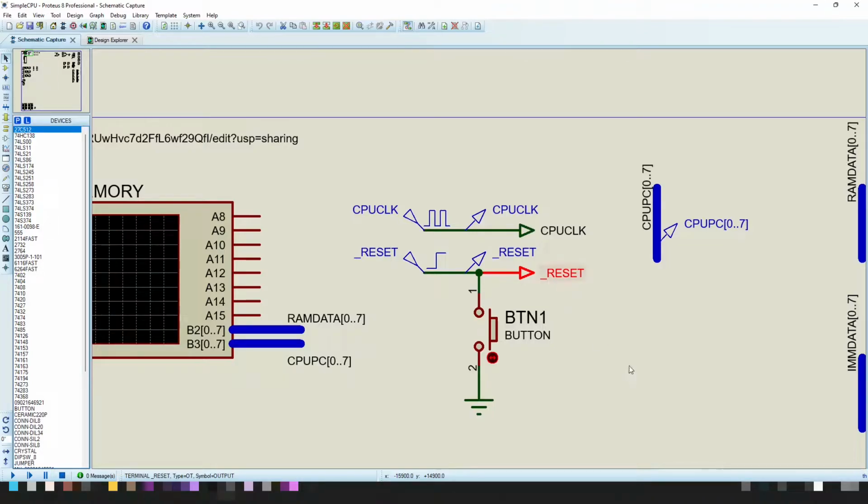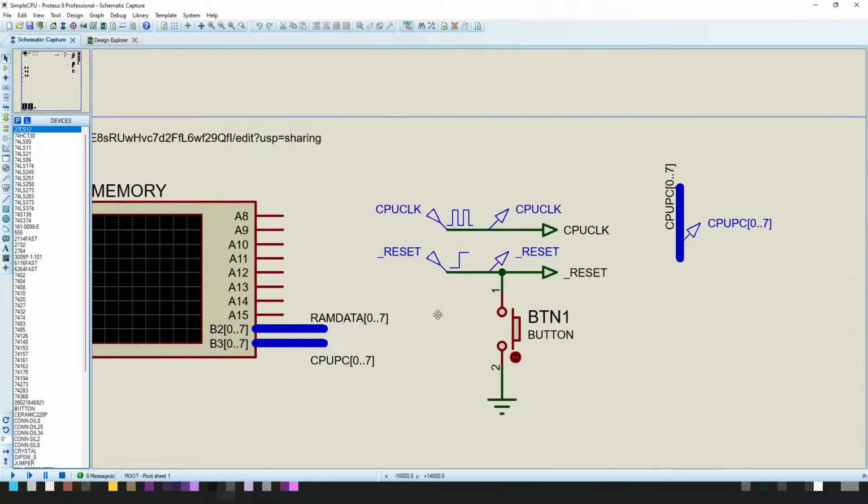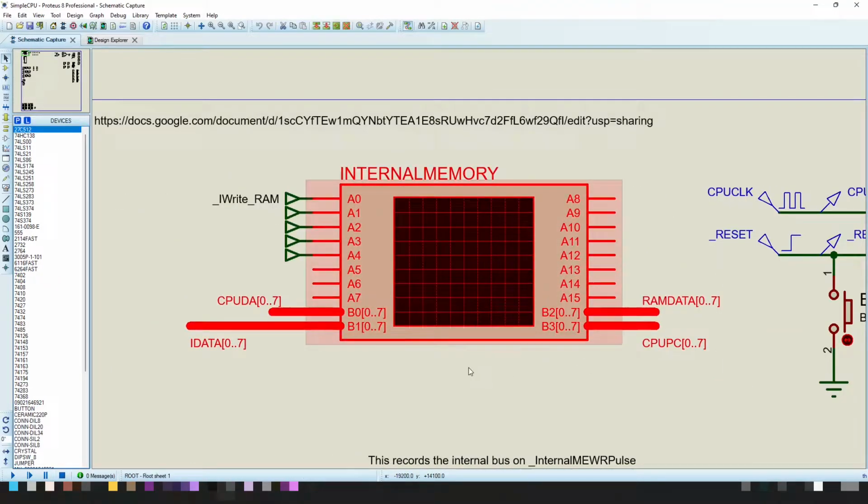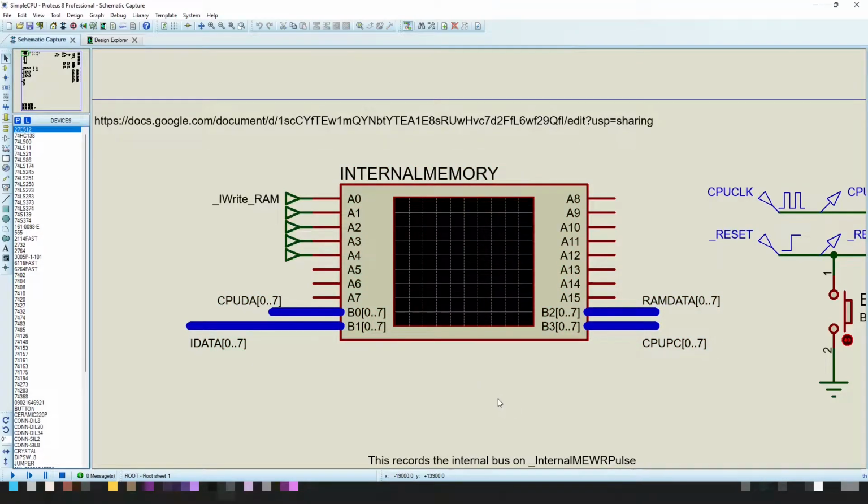So that's the clock generation. Over here is just some connectivity for a virtual logic analyzer, and I can show you this when the actual simulation starts running. But basically, I'm looking at the CPU data address signal, the internal data bus, which is the internal data value that's currently being selected, the value that's coming from the internal work RAM, and also the CPU program counter.